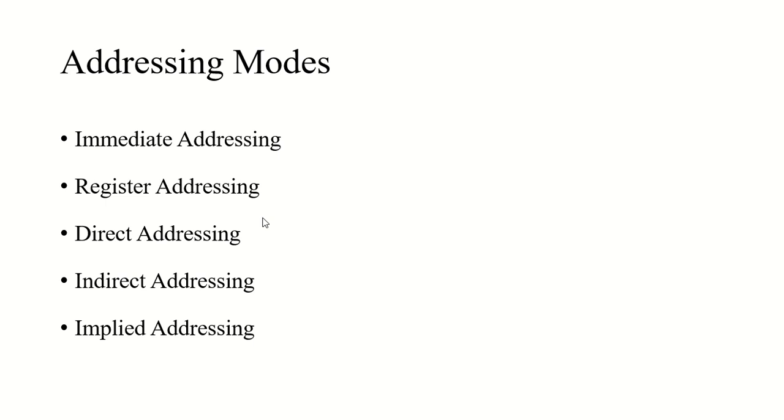And in 1 byte, the instruction includes opcode and operand in the 8 bits only, right? Like single byte. And the 1 byte instruction specifies the operation to be performed and who is going to perform. Simple, nothing else, just the operation to be performed and who is going to perform. So it is in opcode format, because of course we are having only 8 bits, so there will be no other operation or instruction except for the opcode. And when we go for 2 byte, we go for 16 bits, and we get opcode and operand both together.